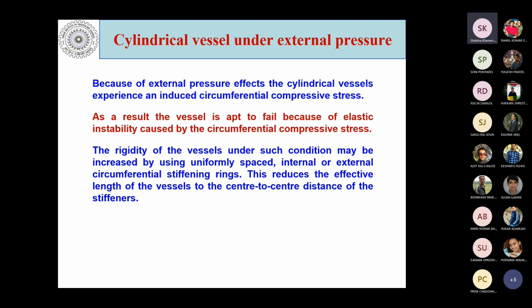Let's say my total length is 10 meters. This circumferential compressive stress is acting along this 10-meter length. However, if I put a stiffening ring after a regular interval, say 1 meter, then the area which remains without any support is only 1 meter. Before it was 10 meters.